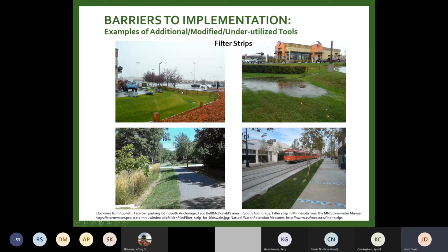If you had a different application where you didn't need curb here, you could just send water directly down this side slope. There's your filter strip and there's your treatment. So pretty simple concept. This is a similar situation, this picture on the top right here. Again, water coming in through curb cuts that come down. This is not a design failure. This is an elevated inlet. This is done on purpose. They're actually getting some detention here as well as treatment.